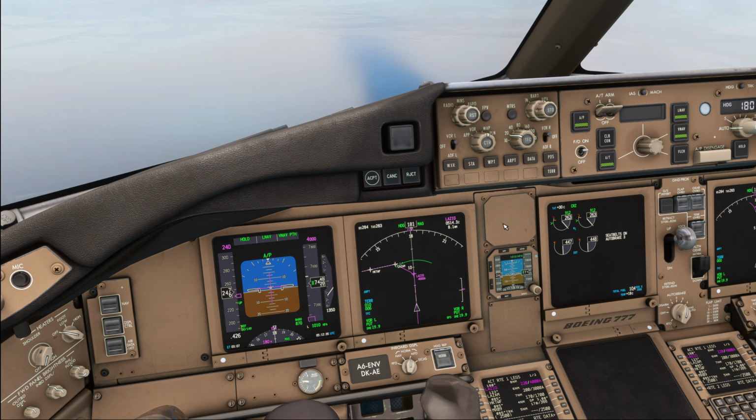This concludes our preparation. Now, when we conduct the actual approach, first of all, we have to ensure very carefully that we are on the correct QNH. There is no monitoring for altimeter error in the Boeing 777. So if you accidentally select an incorrect QNH, you will end up on an incorrect flight path.